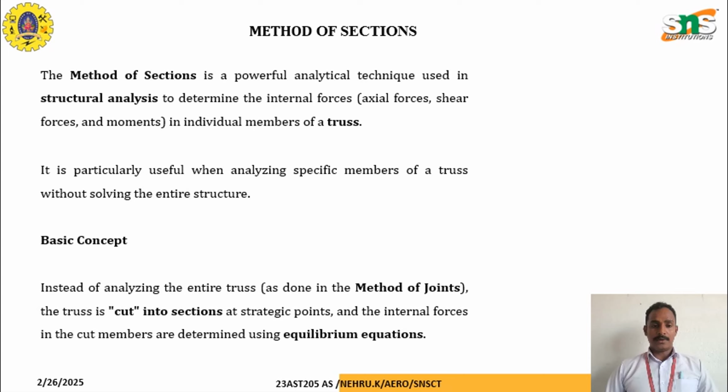The concept in the method of section: instead of analyzing the entire truss, like we did in the method of joints, the truss can be cut into sections at strategic points, and the internal forces in the cut members can be determined by using equilibrium equations. It can be used for very large trusses.